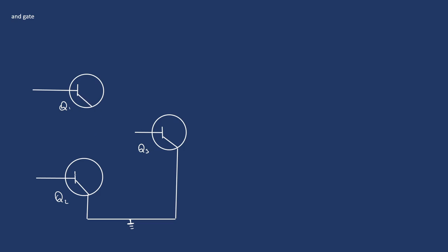Okay, so the neat trick about using transistors for an AND gate is that the emitter of Q1 is directly tied to the collector of Q2. Okay, so that's how they directly depend on each other, so that they are connected in series. All right, so then we take the collector of Q1 high, then we know we're going to raise this to 5 volts. But for that, we definitely need to add a load resistor. Without the load resistor, we won't get the voltage drop we need. Okay, so we put our load resistor,